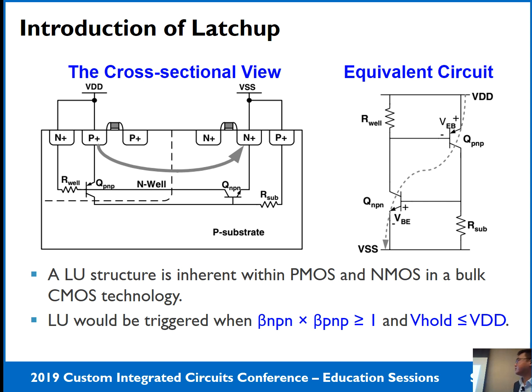The latch-up structure is inherent in the simple inverter structure. From the PMOS source to the NMOS source, there will be a PNPN SCR path between the VDD and the VSS. Once this device turns on, you will have a strong current leak from VDD to VSS.